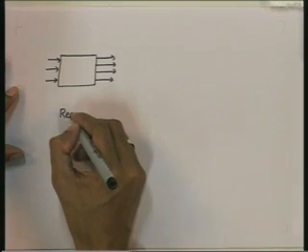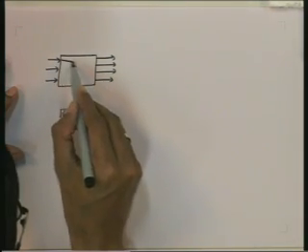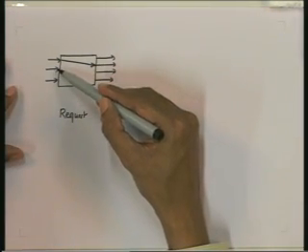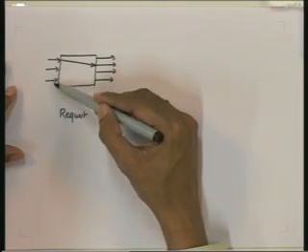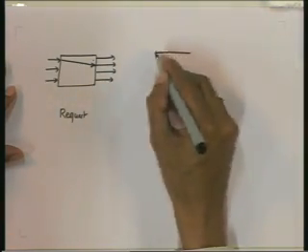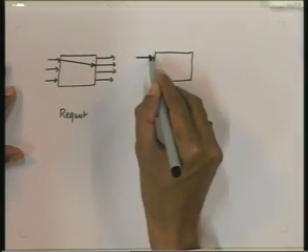This is the request phase, and input port 1 sends a request to output port 2. Note that input ports 2 and 3 cannot send requests because they still have a packet to be transmitted to output port 1. Now this is the grant phase, in which output port 2 will give a grant to the input port.